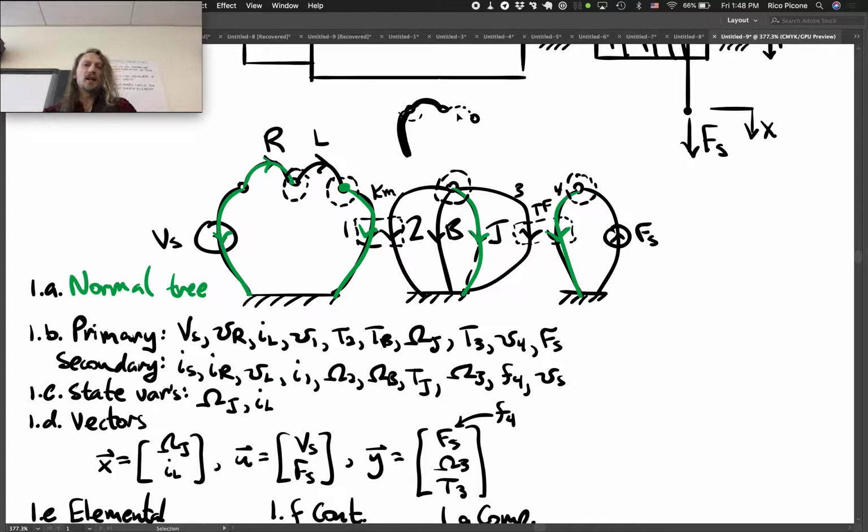So instead, you have to do this contour, because this one just intersects a link. Oftentimes it's just the node. Like in this case, we just wrote 4 node equations, right? But occasionally you'll want to do a contour that includes multiple nodes.